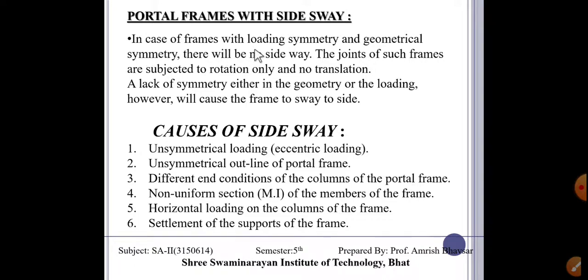In the case of a frame with symmetrical loading and geometrical symmetry, there will be no side sway. The joints of such a frame are subjected to rotation only and no translation. The lack of symmetry in either the geometry or the loading, however, causes the frame to sway sideways.